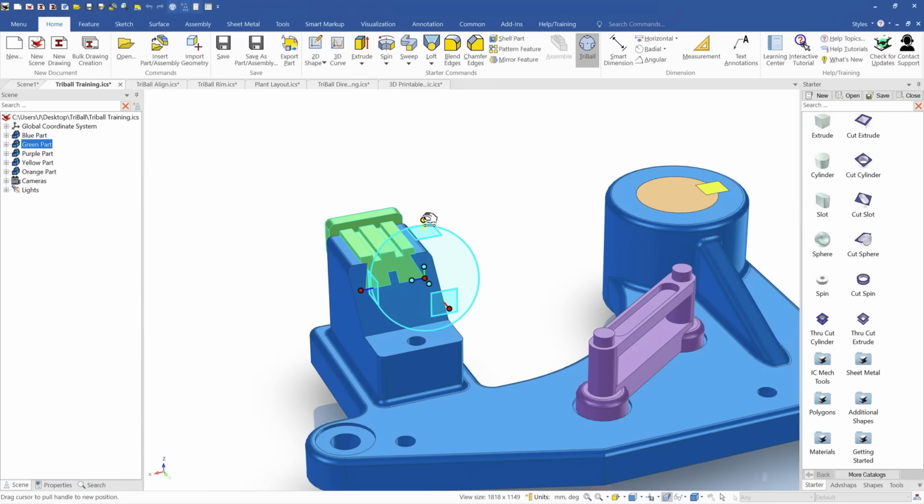If we right click on the external handles, we can move. So these are for moving. So external handles for moving, internal handles are for aligning. So here we can right click and we can move to point, to the center point, or to the midpoint of an edge, or we can edit distance from point, and so on.